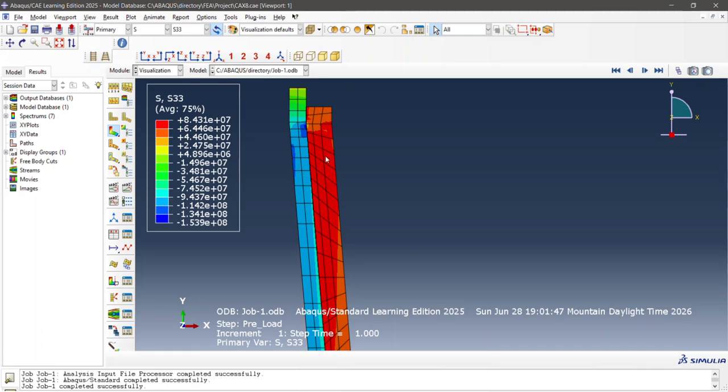And on top of that, the radial tension from the hoop stress is going to apply that compression in the mast, and that's what we're seeing. That's a reaction coming from these stresses being applied into your hub, generating that hoop stress. That tension hoop stress is giving you a compression in your mast. And that's really cool to see that behavior, kind of what you're anticipating.